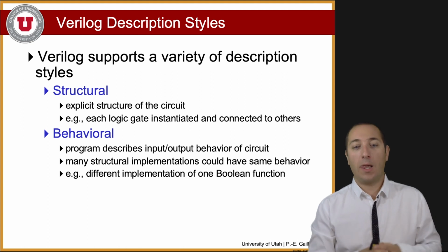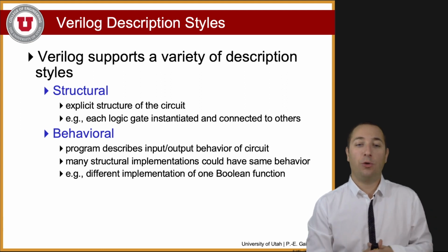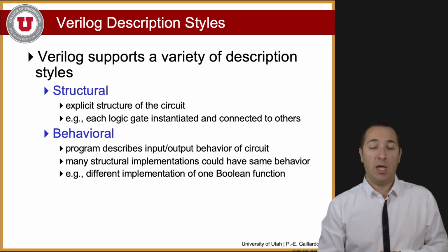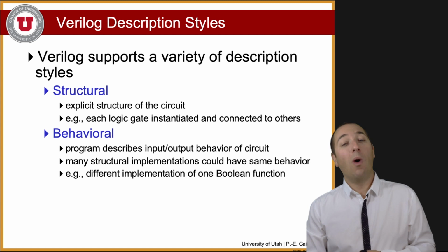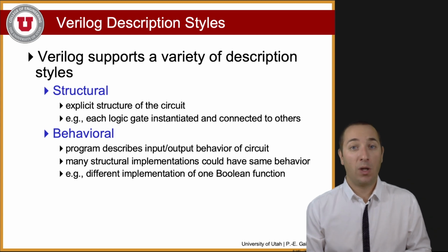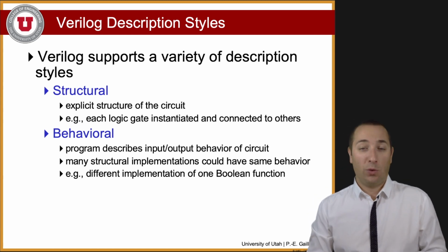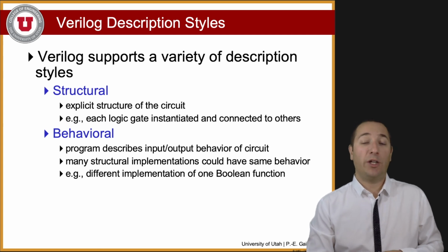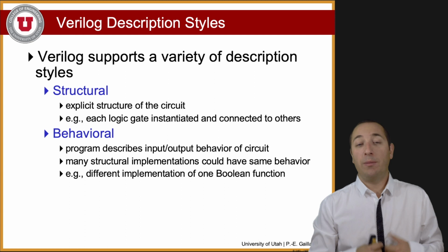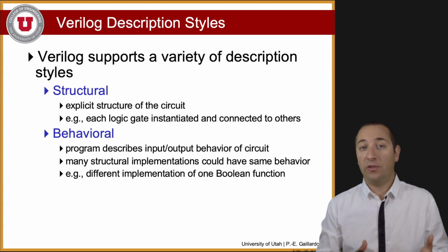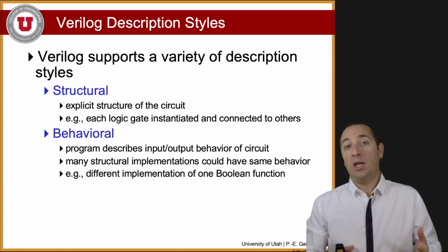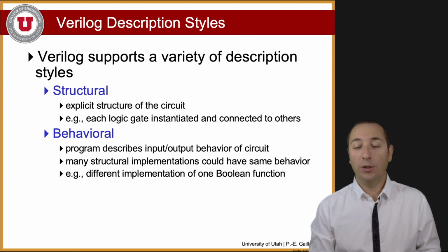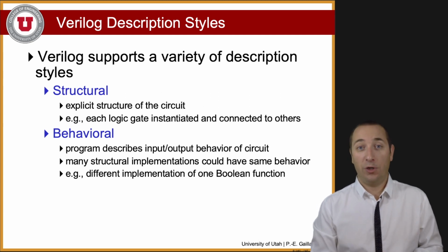And many structural implementations could have the same behavior. For example, if I write in my Verilog, y is equal to a plus b, a plus b is a behavioral description. I am performing an addition between the vector a and vector b, but I'm not providing details on how this addition should be done. Is that going to be a ripple carry adder? Is that going to be a carry look-ahead adder? The synthesizer will decide for you.